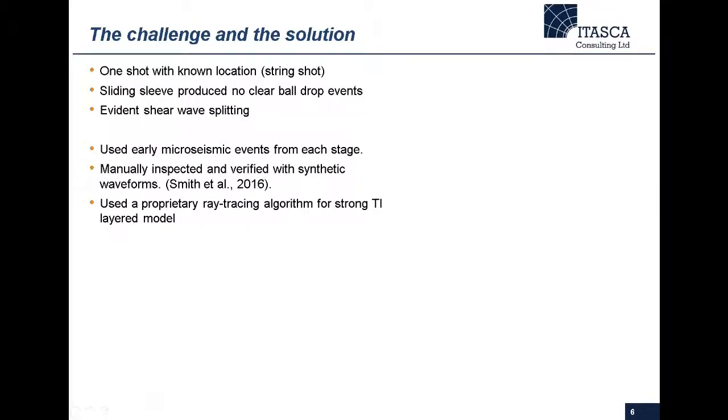There are a few challenges in this project. Number one is, as I said, there's only 1 shot with no location, and it's not a perforation shot. The completion method is sliding sleeve, so there are no clear plug job events that were ever recorded.